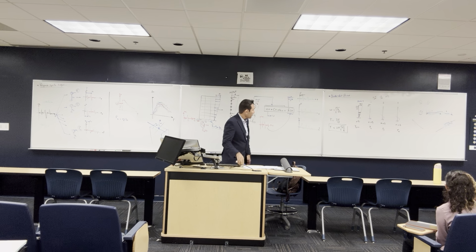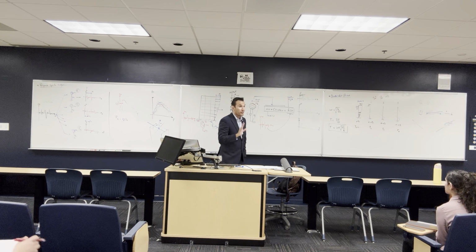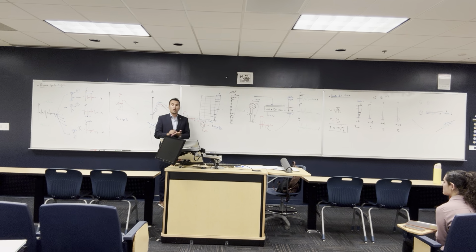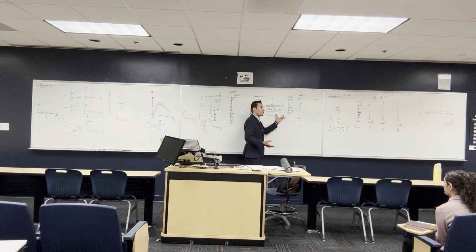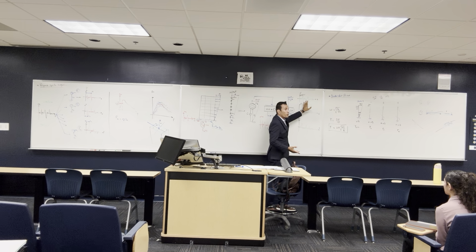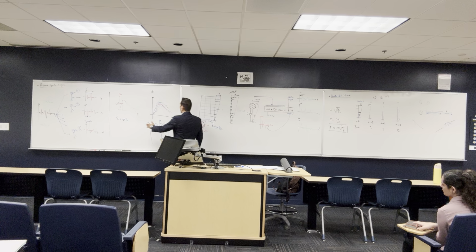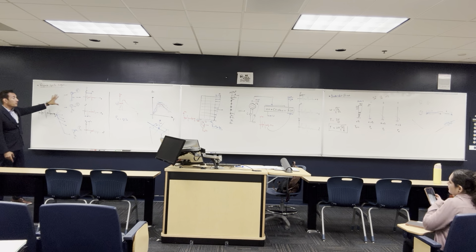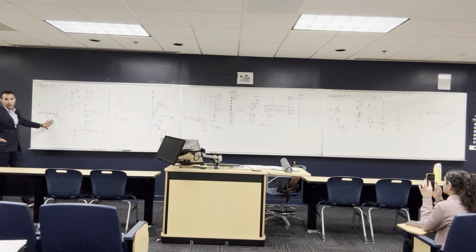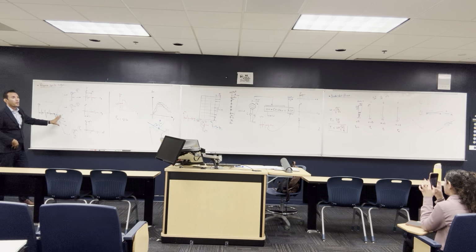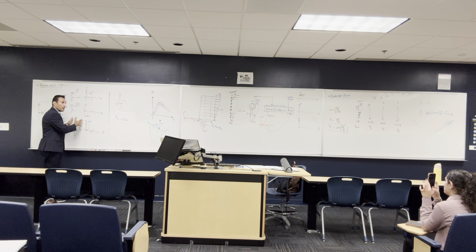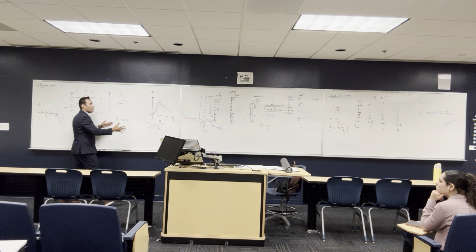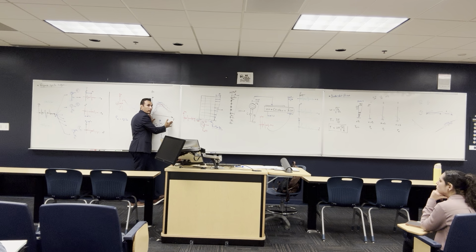Okay. All right. You guys want to take pictures of this? Because, by the way, the exam is not solving a problem. I'm going to ask you to describe a process. Describe how a building can be converted from multi-degree of freedom to single degree of freedom, to write the equation of motion, the solution of the equation of motion, the response spectrum analysis method. Maybe I'll ask you to describe this process. This is for the final exam. How to do response spectrum analysis. We have a ground motion of an earthquake, we apply it to a spectrum of buildings, we get the responses of the building, and then we draw a response spectrum curve. Okay?